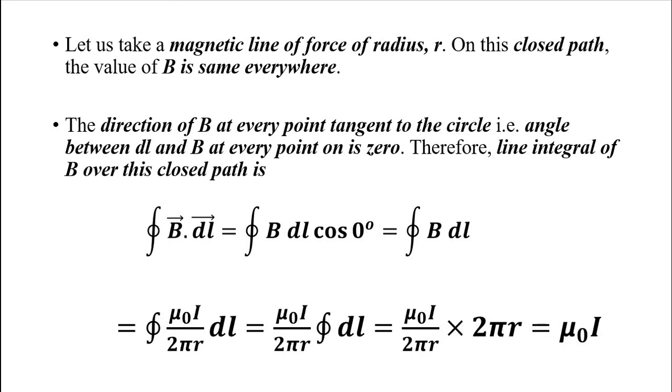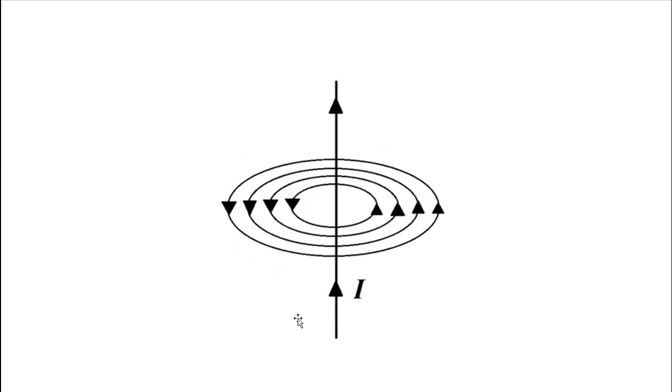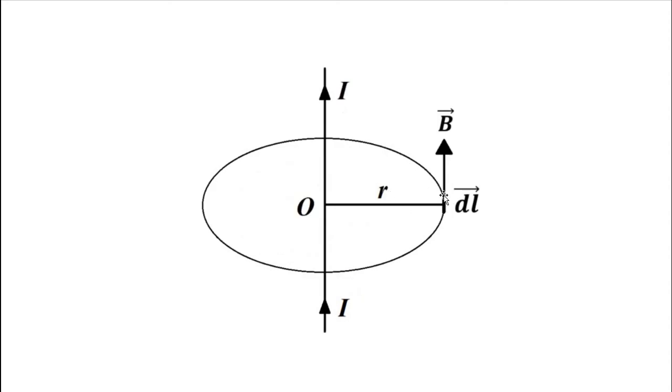Okay, so here the magnetic field line encloses this wire carrying current I. The current flows in a straight line path through this wire. The magnetic field lines are concentric circles. We picked a certain concentric magnetic field path of radius r. The magnetic flux density is in a mutually perpendicular direction with respect to it, as per Biot-Savart law. And we just performed the closed line integral.